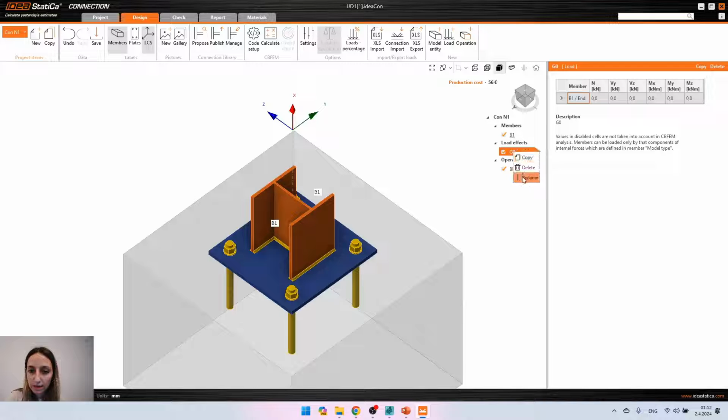I will change the name to M epsilon, and I will have to insert a value of the stiffness in here. This value, I will set it to 1.5, and this is a random value. This is because whatever value you apply in here, you will always get the same initial stiffness. So you can input any random value that you can think of. And this is all that you need if you want to calculate the stiffness around the epsilon axis.